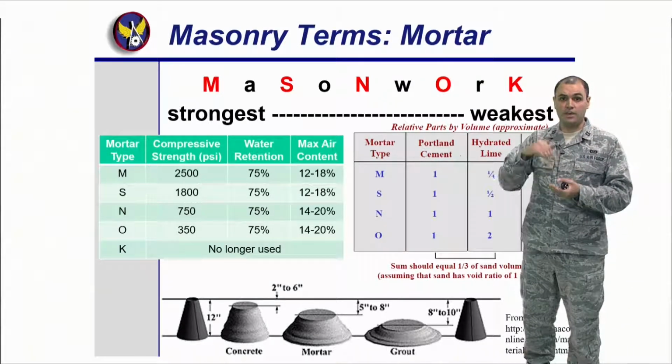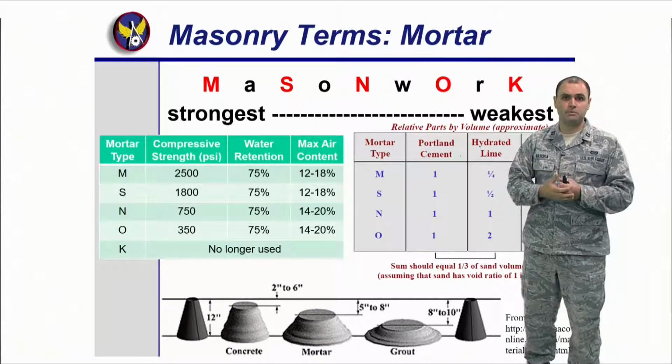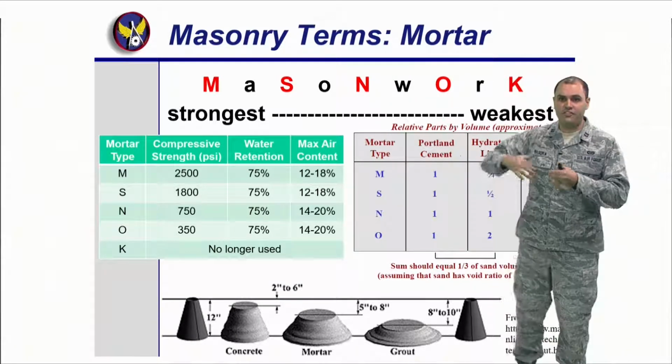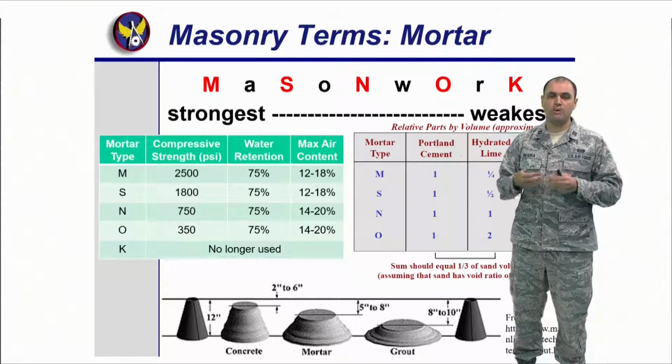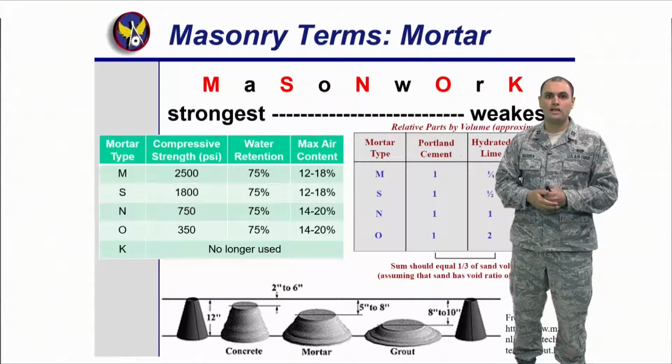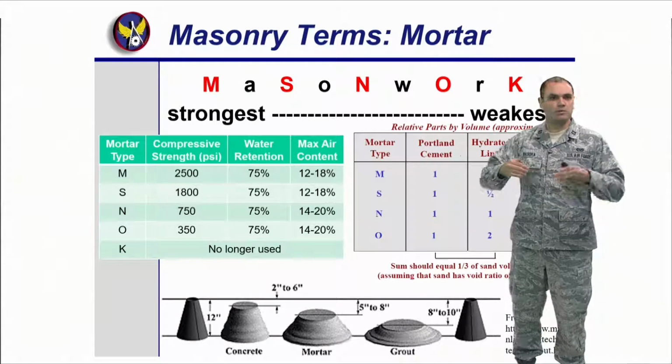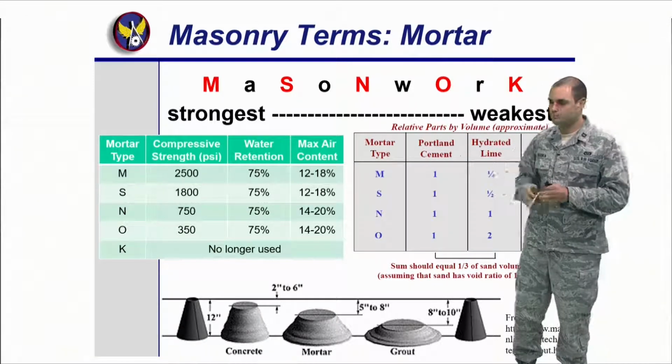So if we're going to fill that with a reinforcing bar, or we need additional strength, we're going to make it a little watery so we can fill all those little voids, right? Ensure that we have the strength that we need and the cross-sectional area that we need. If I don't have it too watered down, I'm not going to be able to fill all those voids, right? That's kind of behind it.